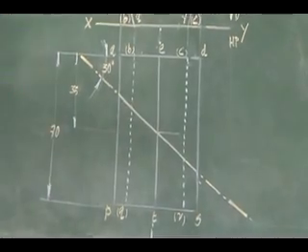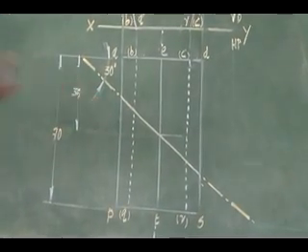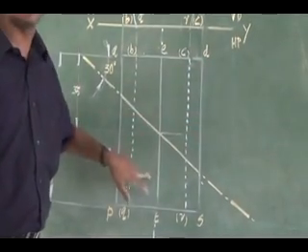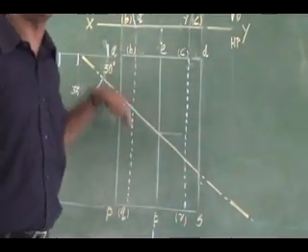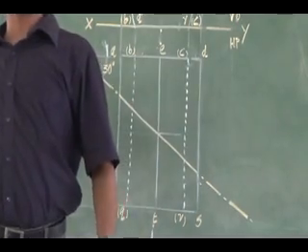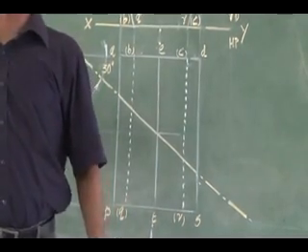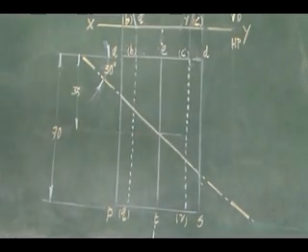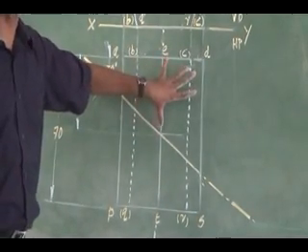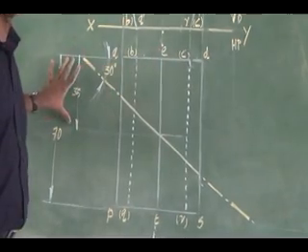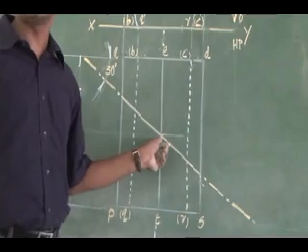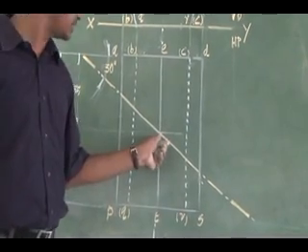Then as for the cutting plane representation, since the cutting plane is perpendicular to HP, I have to represent my cutting plane on HP. So I have shown the cutting plane here, and the cutting plane inclination is 30 degree, and it is exactly bisecting the axis. Since the axis height is 70, bisecting means 35, exactly in the middle of the axis, that is 35 from the base.